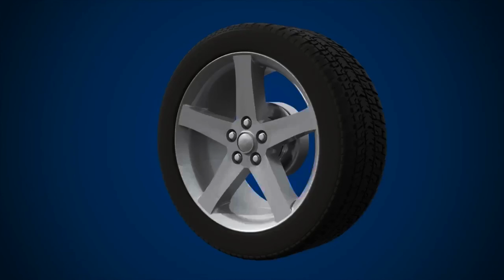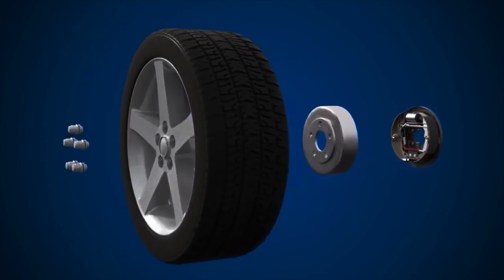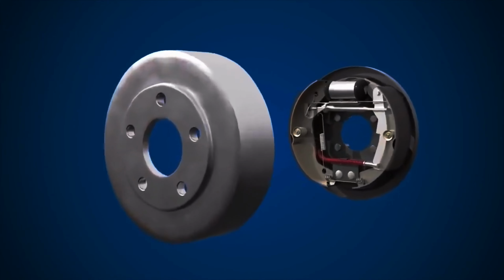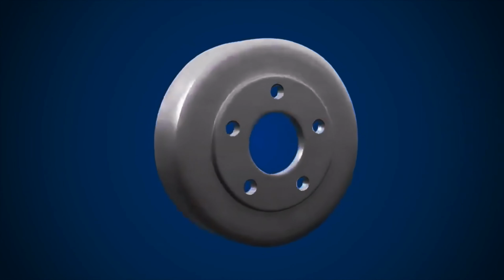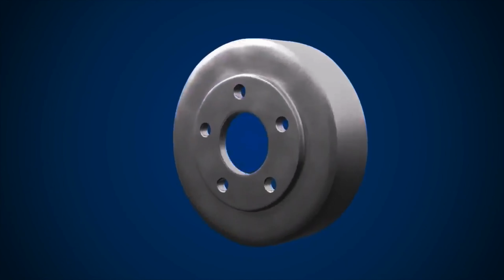Let's take a look at the components found in a typical drum brake system. We have the back plate assembly, the brake drum, the wheel, and the wheel nuts. First, we will take a look in more detail at the brake drum and back plate assembly. Brake drums are generally made of cast iron, which conducts heat well and is slow to wear. The drum rotates on the axle and wheels, providing the friction surface when the brakes are applied.